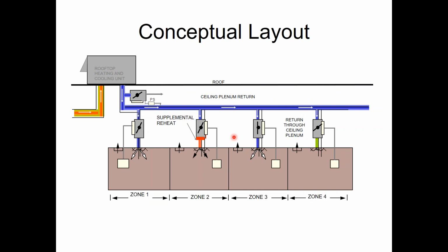If any one of those zones asking for cooling gets warmer, let's say 2 degrees above set point, so it's 75 in the room on a 73-degree set point, then it's going to ask the rooftop to provide 2 stages of cooling. But I'm not directly controlling the discharge, in which case I'll probably get 55-degree air. So I only have 2 stages to work with.